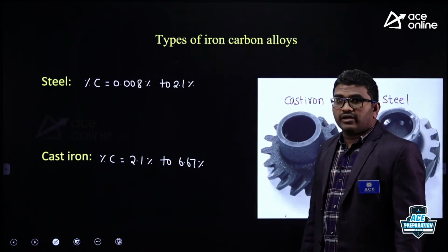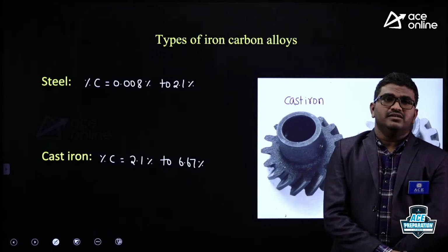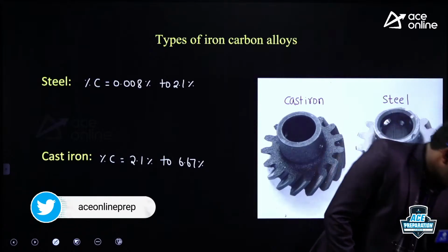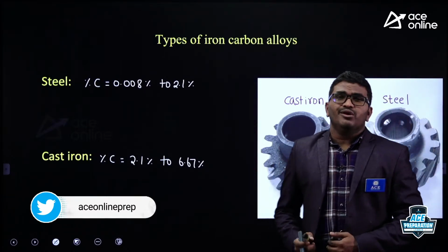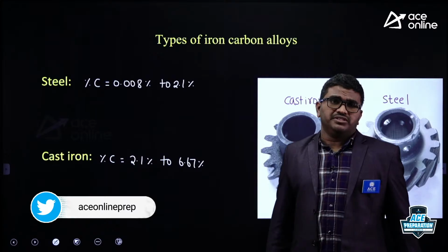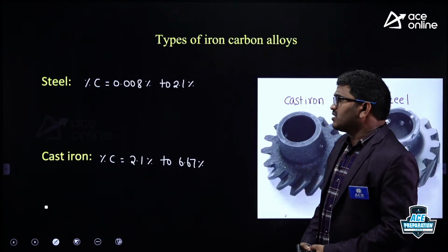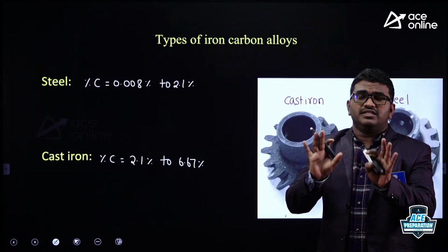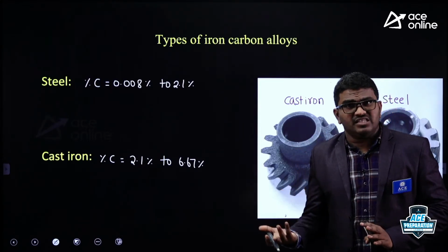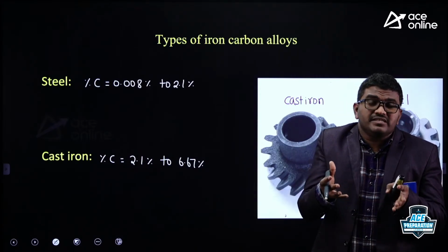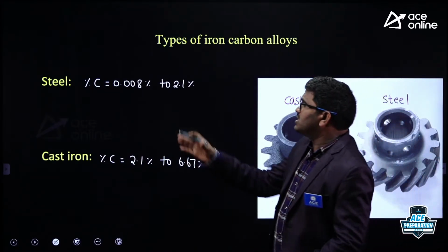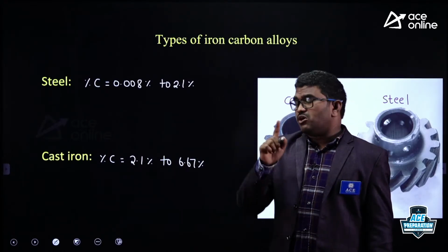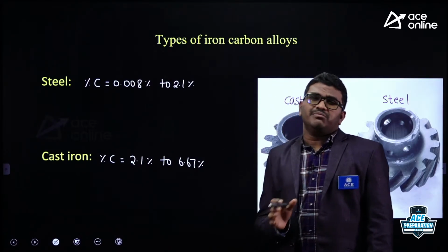Do you know? Okay. As a mechanical engineer, you should remember this general basic question. So, what type of questions will they ask, you know? What is steel? This type of question. Most of you people think that steel is an iron carbon alloy, that's it, and will give only that. Cast iron is also an iron carbon alloy, but the percentage of carbon you should mention. Some of you people will say that steel is an iron carbon alloy with carbon percentage 0 to 2.1. It's not correct actually. 0% of carbon is not a steel.